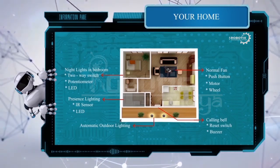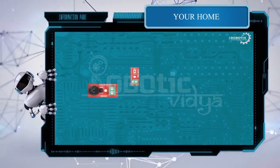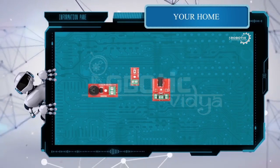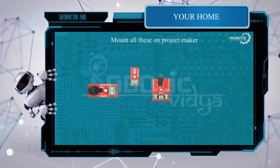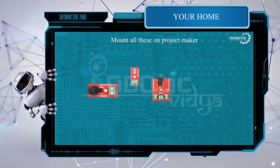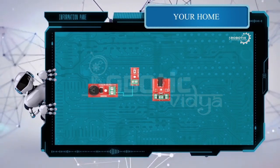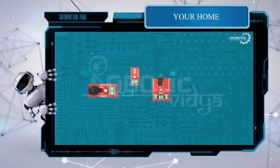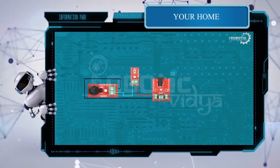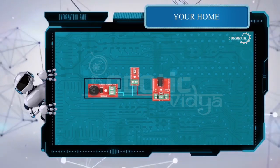So the items that we required were a momentary switch, that is a reset switch, and your buzzer. Of course, your power supply board is also required. So mount all of them onto your project maker and get ready to start the connections. Now it's a very simple connection. Connect any terminal of your switch to the positive of your buzzer. The other terminal of your switch goes to the positive of your power supply board, and the negative of your buzzer runs to the negative of your power supply board.